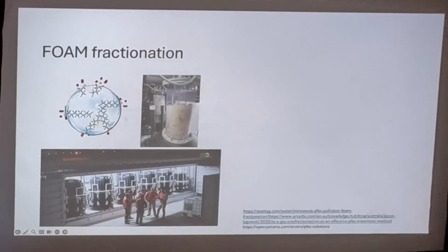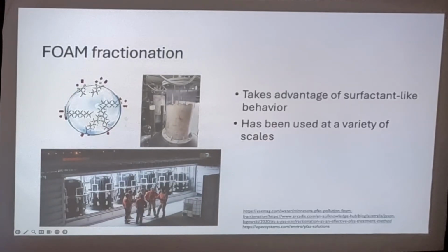Foam fractionation, this is a big one. People are spending a lot of effort. As I mentioned earlier, most PFAS have this long carbon-fluorine tail. They're very soap-like, so if you bubble gases through water, you can remove them from the water. And there's commercial processes, several companies working hard at this. Works well for landfill leachates and other concentrated streams. Removal is chain length dependent, so the shorter chain compounds, the probably less toxic ones, are not removed as well.